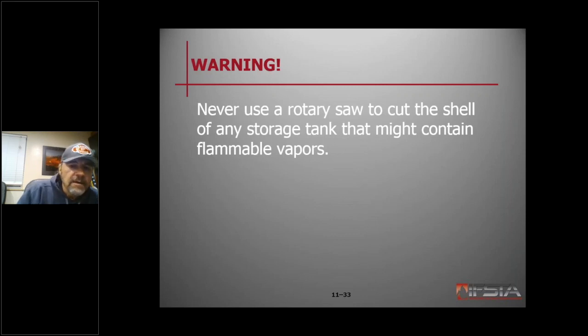This is an obvious no-brainer, but there may be some instances where a worker has been trapped or may have gone unconscious inside some compartment in a commercial building, perhaps. We have to be aware what is stored in that compartment. Why did the person go down? Are they overcome with carbon monoxide, or is it maybe fumes from something that's flammable?